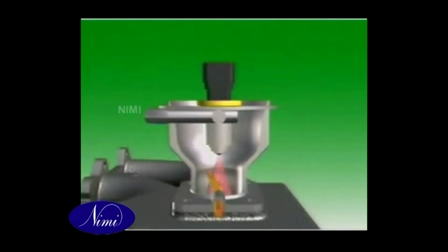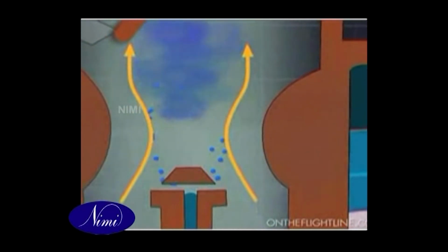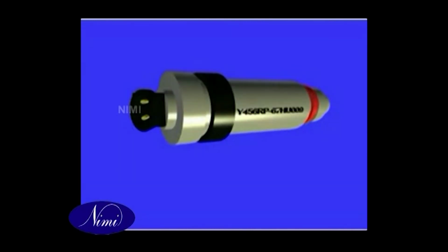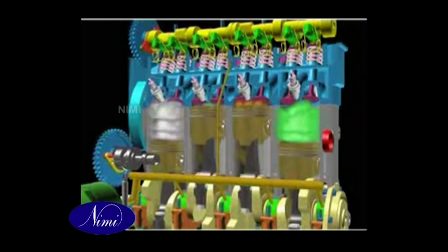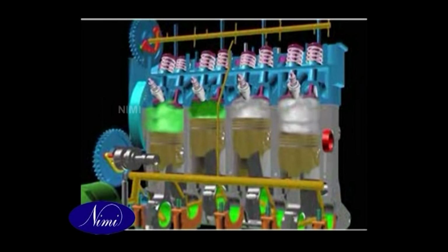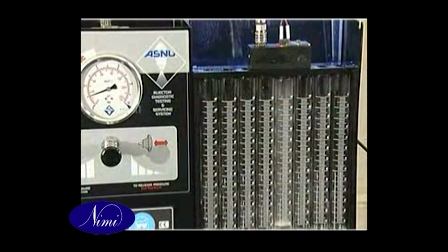The primary functional difference between a carburetor and fuel injection is that fuel injection atomizes the fuel by pumping it through a small nozzle under high pressure, while a carburetor relies on low pressure created by intake air rushing through it to add the fuel to the air stream. The fuel injector is only a nozzle and a valve. The power to inject the fuel comes from farther back in the fuel supply, from a pump or a pressure container. The process of determining the amount of fuel and the delivery into the engine is known as fuel metering.